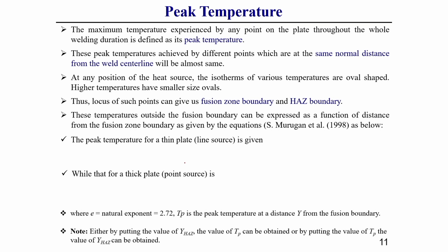Now, we will discuss the concept of what is called peak temperature. This is a very interesting phenomenon. Based on the two dimensional heat equation and the three dimensional heat equation, you can again calculate the peak temperature of a particular location achieved during the entire welding process. What does peak temperature mean?